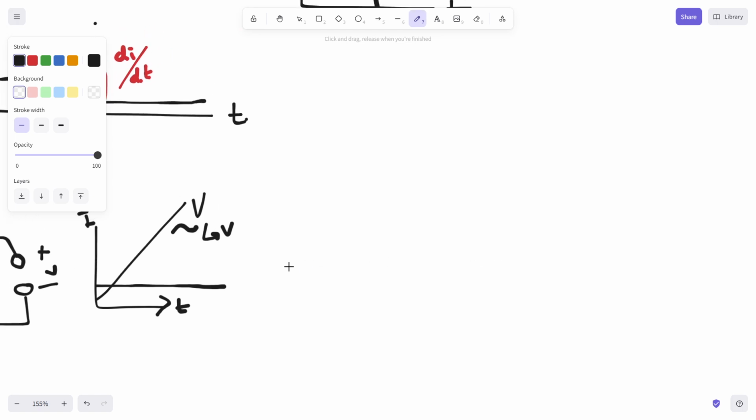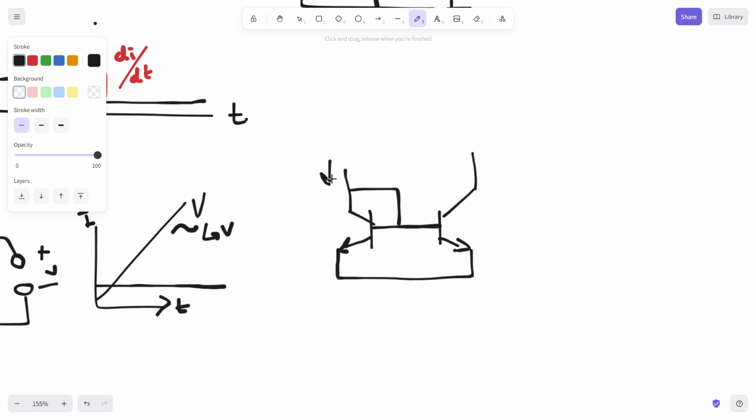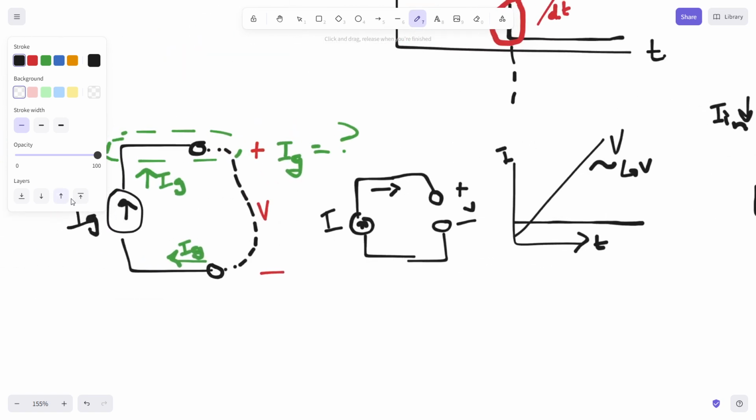But if we talk about an actual circuit implementation, let's go back to a BJT example. So here we have just a simple current mirror, which can be thought of as a current source. In a current mirror, you really have some kind of input current, and then you generate some kind of output current. This would be considered a current sink because you're sinking current to ground. Just think about if this arrow were drawn to face downward.